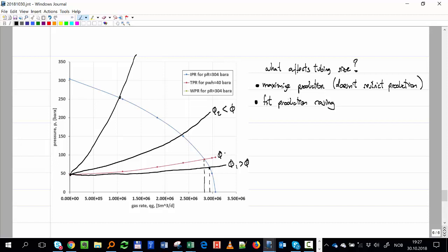One of them, you want to maximize production such that the tubing won't be a constraint. Like if the rate you want to produce is someplace here, you want to get a high production from the well, but you are here, that indicates you are restricted by the tubing. Okay, it's tubing restricted. If you are here in that range, that means you're not tubing restricted. Your tubing is too large. So you have to be someplace in between. Big tubing costs money, and to replace the tubing costs money. So you have to use a size in between, not too large and not too small.